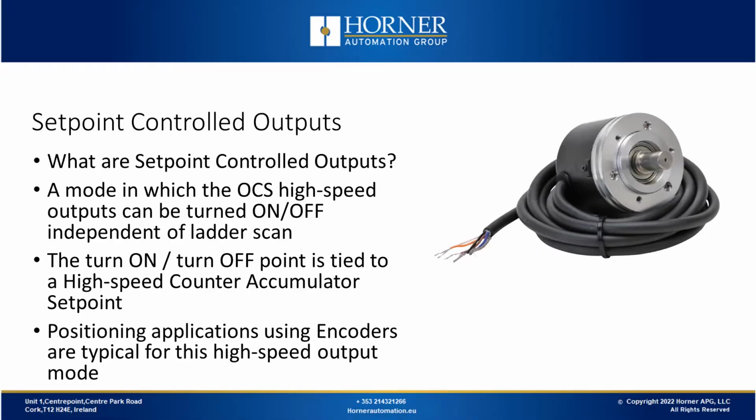Next, let's look at a setpoint controlled output. What are setpoint controlled outputs? This is a mode in which the OCS high-speed outputs can be turned on or off independent of ladder scan. The point where they're turned on and off is tied to a high-speed counter accumulator setpoint.